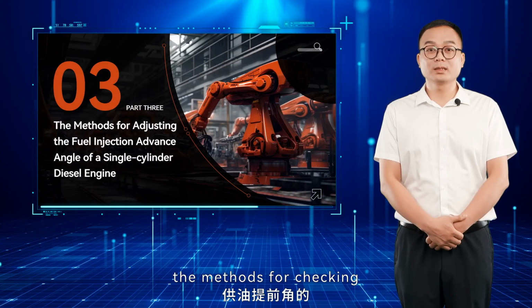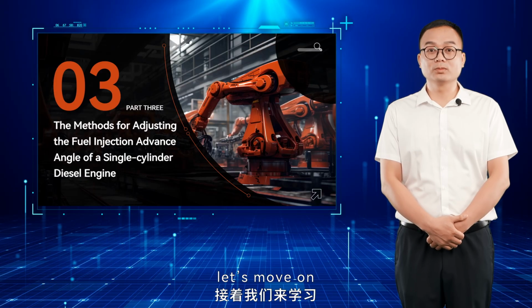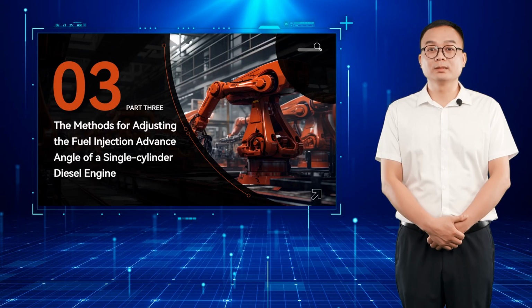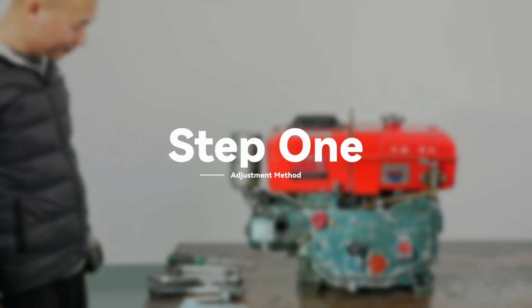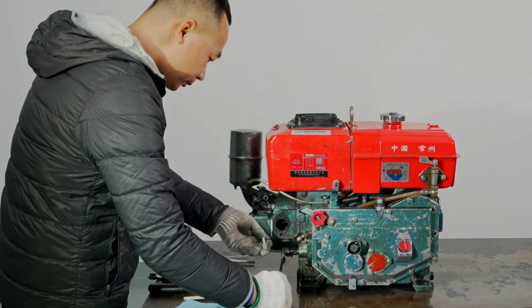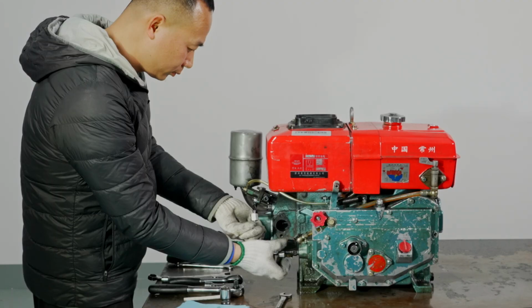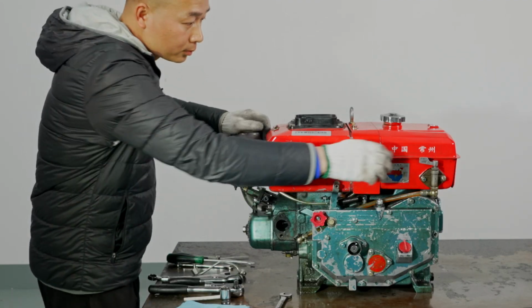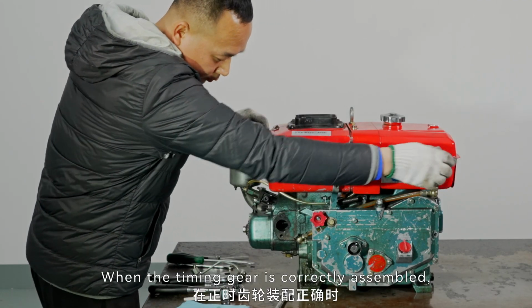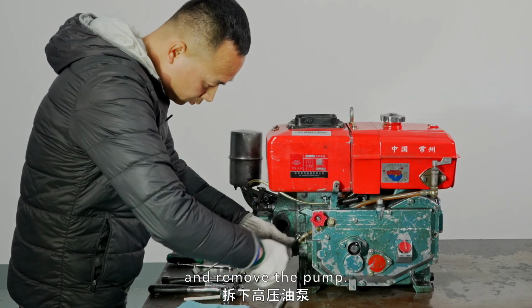Now that we have covered the methods for checking the fuel injection advance angle, let's move on to the adjustment methods. When the timing gear is correctly assembled, loosen the 3 bolts on the high-pressure fuel pump and remove the pump.